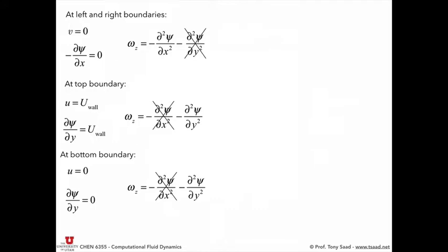So I guess then why could we say that psi was constant? Because d psi by dy, okay, so along the wall, be careful, psi is constant only in the y direction, not in the x direction. So along the y direction, d psi by dy is 0. On the left wall, d psi by dy was 0.